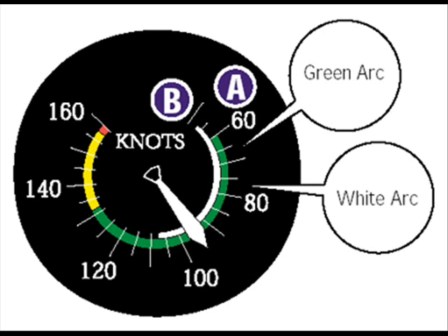You don't get something for nothing. Flaps provide you with lift, but they also produce drag. Full flaps create a low-speed wing. Try to accelerate it at some point, and drag defeats your efforts. Fortunately, the first half of flap travel usually provides more lift than drag. The last half usually provides more drag than lift.